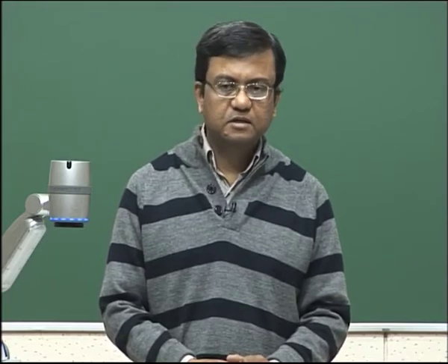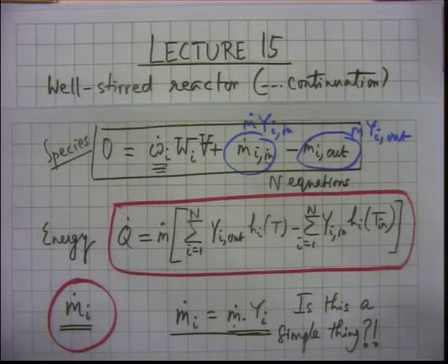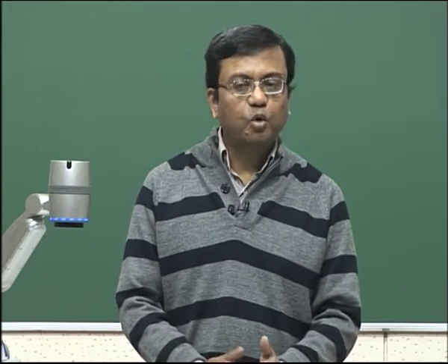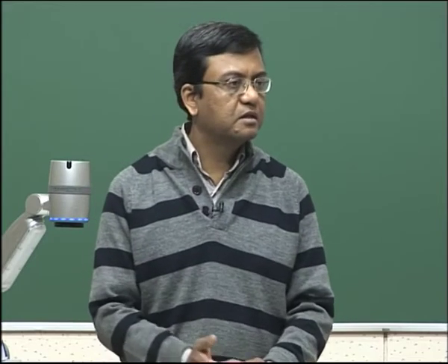So, there is an exit stream, and we said that it is a well stirred reactor. So, the mixing is extremely good, perfect in fact, and at various physical locations inside the well stirred reactor you will have the same concentration, the same reaction rate, and the same temperature, and all these are the same as what you get at the outlet. We discussed this quite a bit last time,